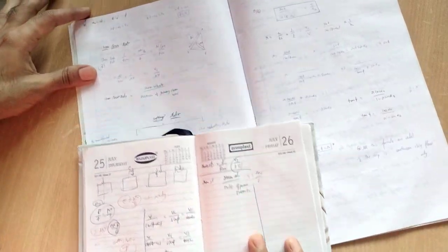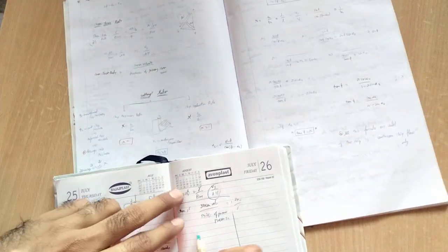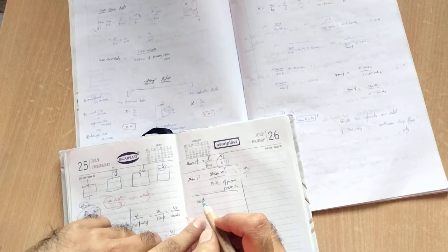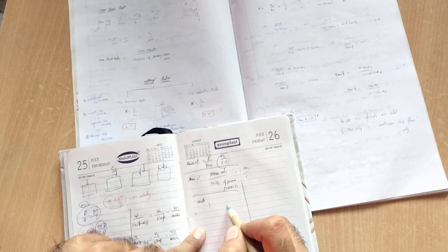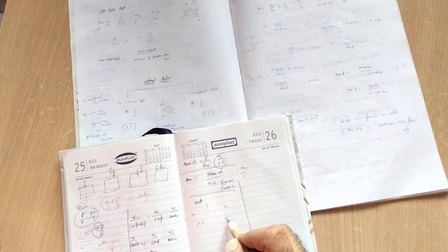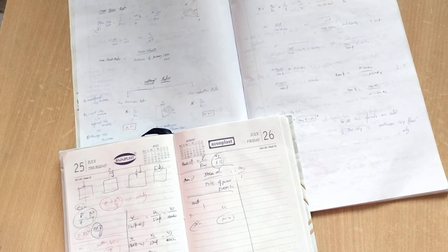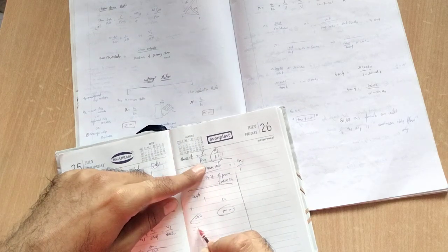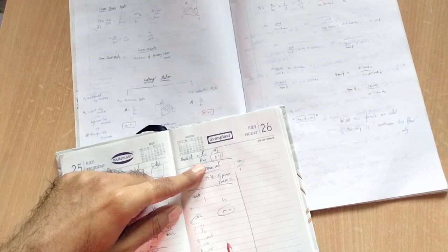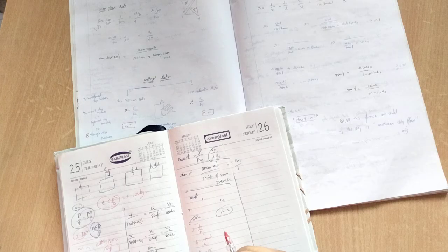So next thing is cutting ratio. You can see one is the chip thickness ratio, the next one is the chip reduction ratio. The chip thickness ratio is generally less than 1, but the chip reduction ratio, R dash, is greater than 1. So R is T1 divided by T2, where T1 is the undeformed chip thickness and T2 is the deformed chip thickness.